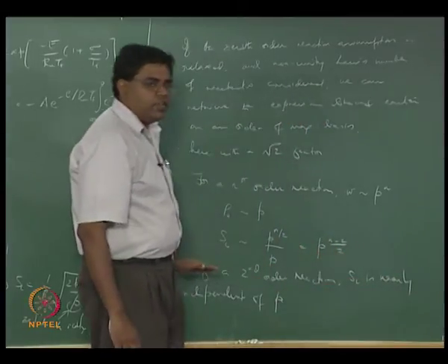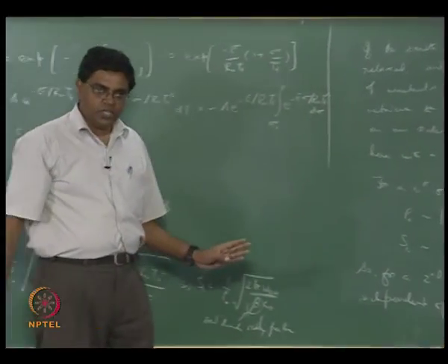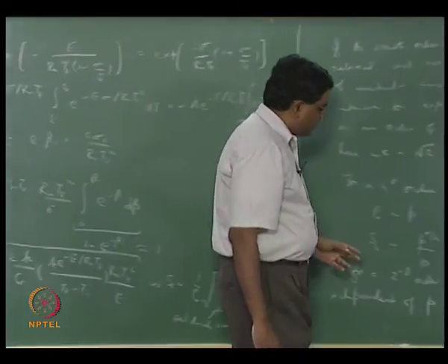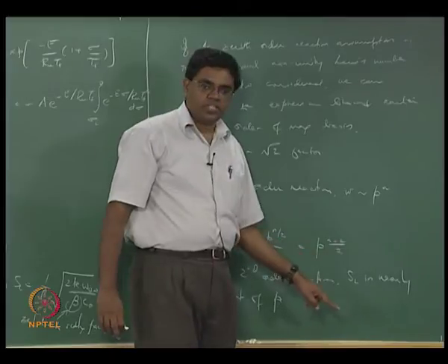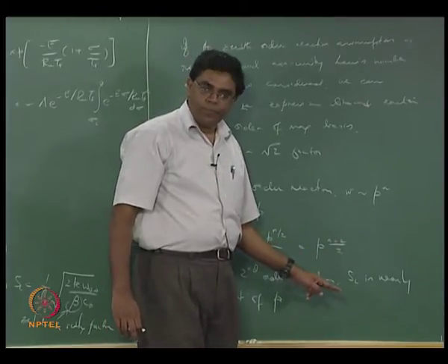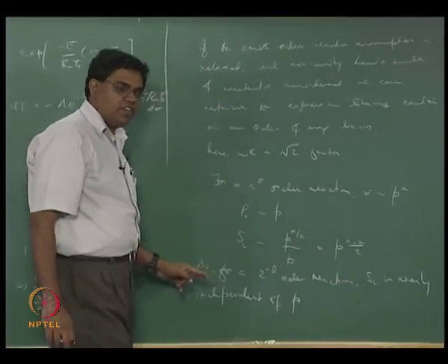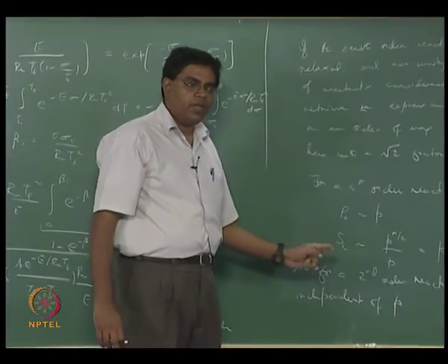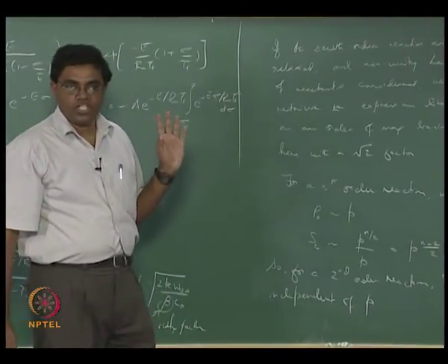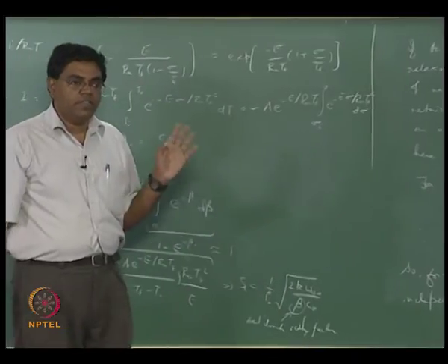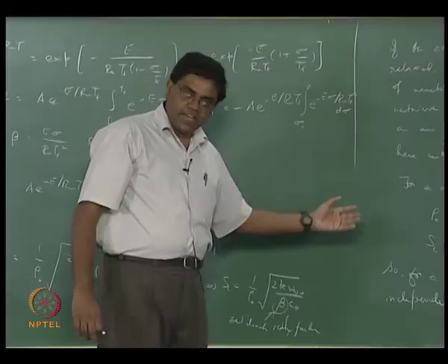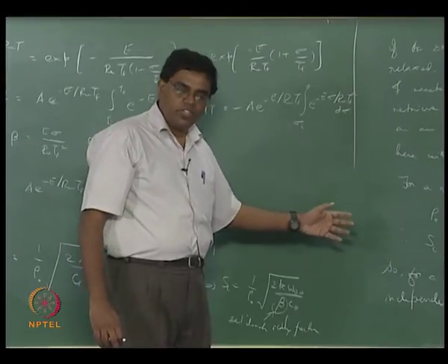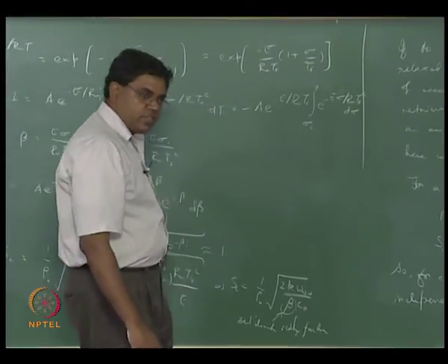So we find that there is a weak dependence on pressure. If you now think about an n that is about 1.8, you're going to have an inverse dependence on pressure, right? That means as the pressure increases the SL decreases, okay, that's in fact what we actually observe, but it's a weak dependence. So we are now beginning to talk about dependencies of S on various factors. What we just mentioned was pressure, which was obvious.